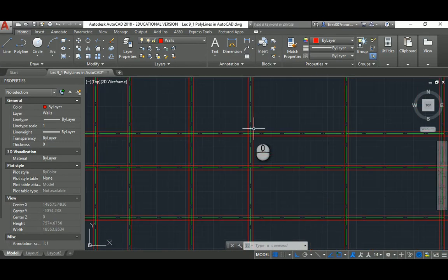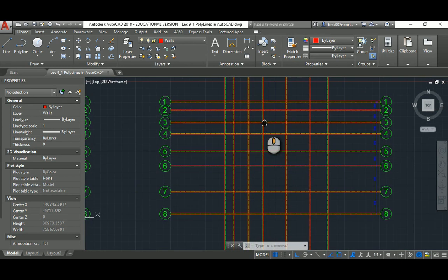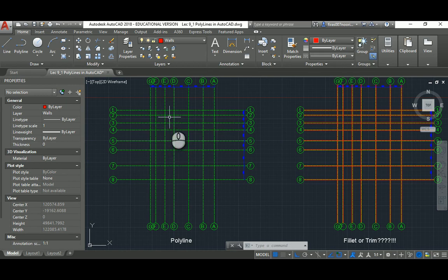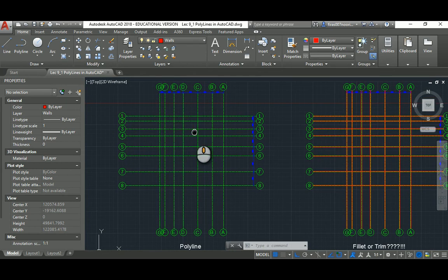the grid lines offset based on 100 and 100 ups and downs, and we have this complicated grid that we need to carve our layout or external wall from by using either fillet or trim, we can use a single line made out as one geometry. It's actually a multiple segment line that acts as one object, and you can create an open loop or closed loop out of it, and that might be very helpful, especially when you offset.